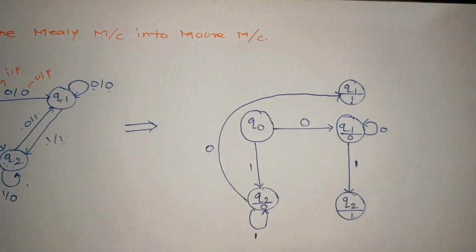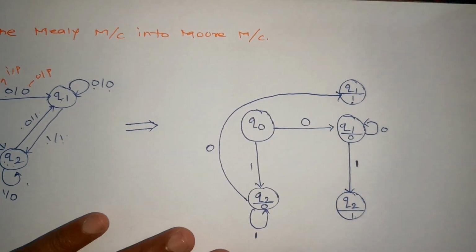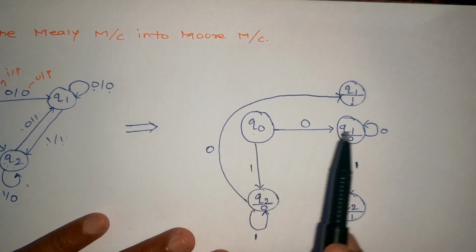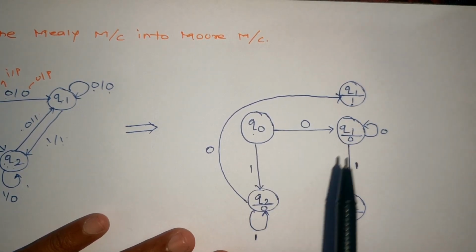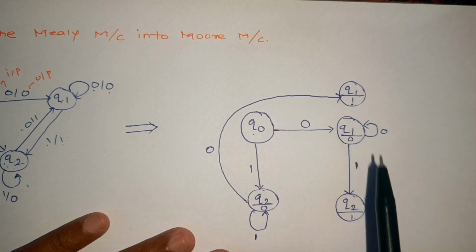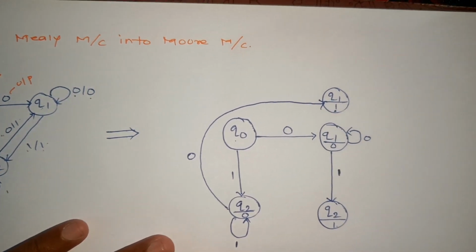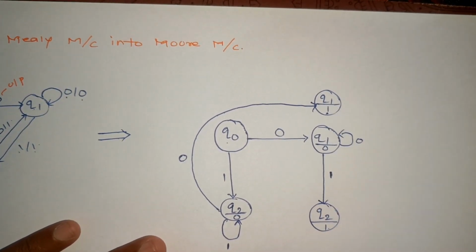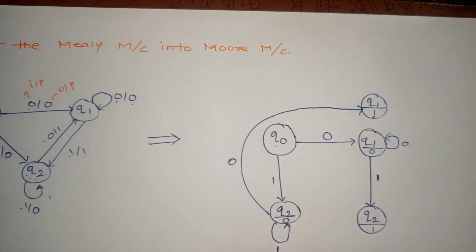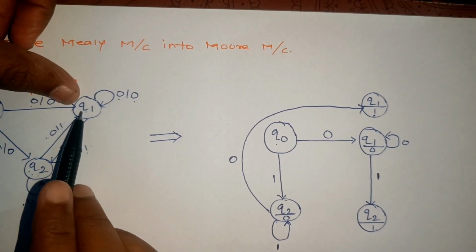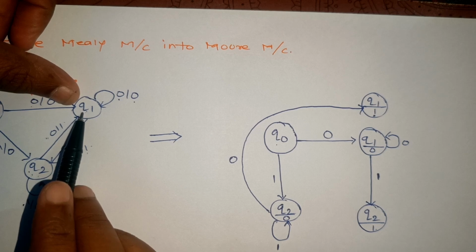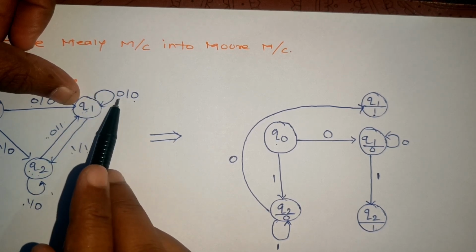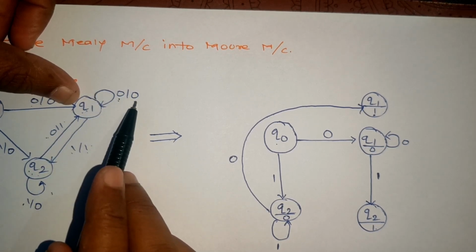अब up to this particular point we got Q0, Q1, Q2. Now we'll switch on to Q1 with output 1, Q2 with output 1. So let's start the possibility of Q2 with output 1. तो देखिए इसके लिए if I see the state diagram, Q1's next state is Q1 provided that input 0 है और output भी 0 है.